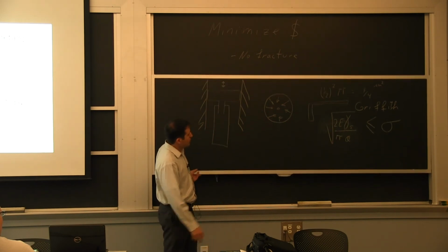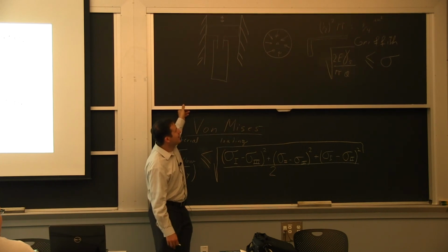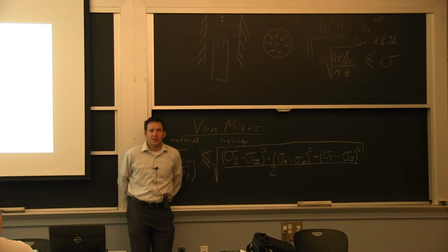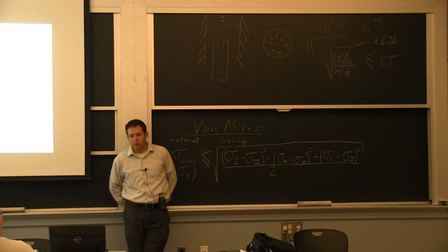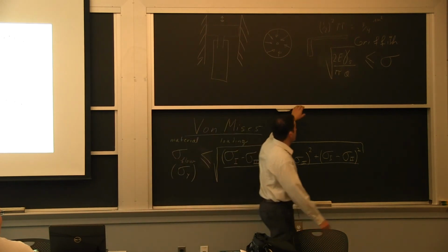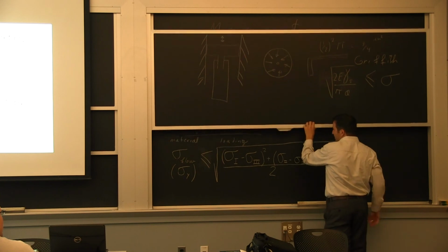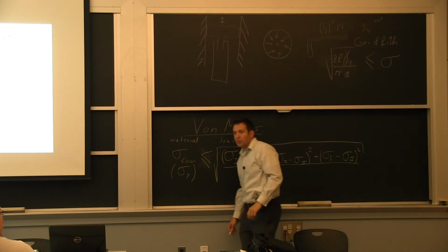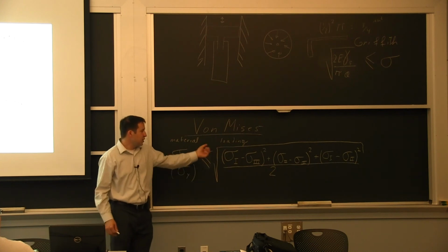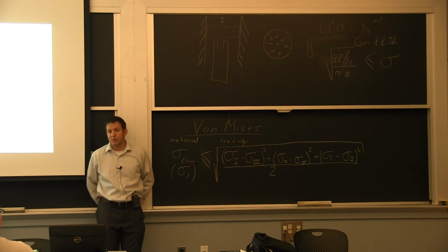So brittle and ductile, there's really not a whole lot of relationship between them. One really has to do with how much load I'm going to put on. I mean, if I keep adding up here, I can have a very, very small defect and it's still going to break. In this situation, if I'm just applying a pressure, even a triaxial tension, I won't yield.